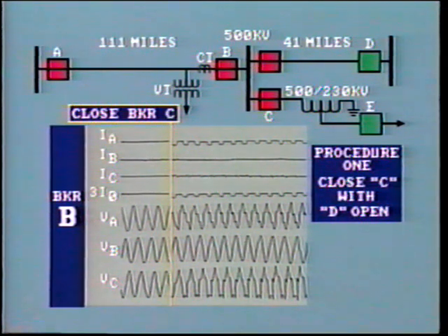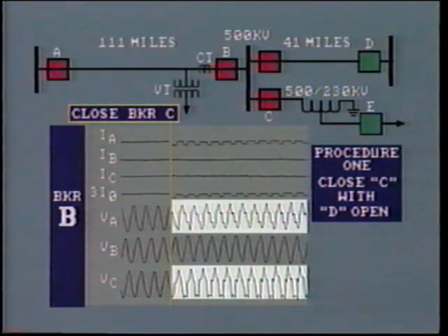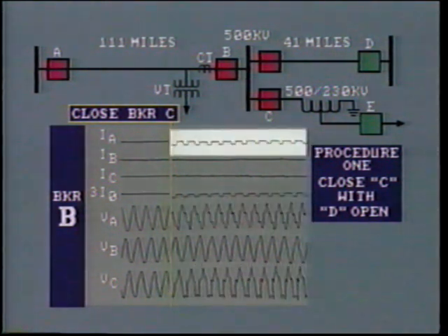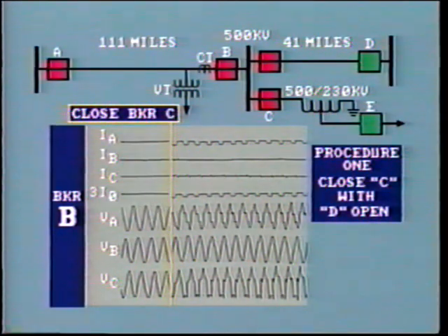This looks quite strange. Voltage VA on the A phase shows some distortion, also VC to a lesser extent. And this current IA must represent transformer magnetizing current. Your workbook explains why only one phase is affected.